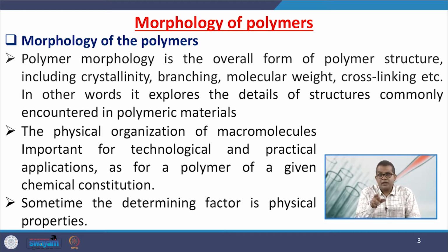Sometimes it determines the physical properties too, like the cross-linking of polystyrene with the help of divinyl benzene, etc. It determines the physical property, maybe a bead-like structure, a film-like structure, a cross-linked nature, or a stiff or sturdy structure of those polymers. So, you have to manipulate things to get the desired properties in the polymers, and the morphology is very important.